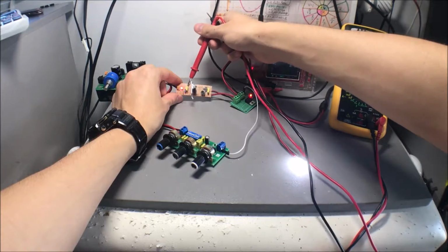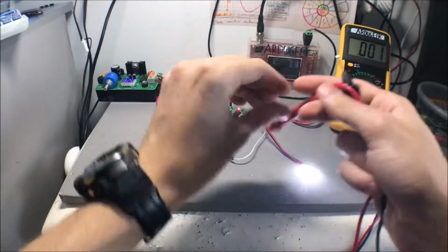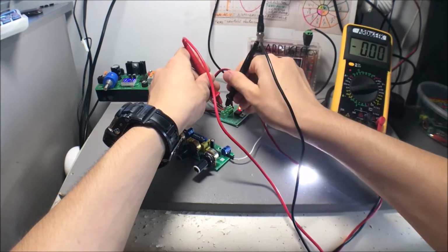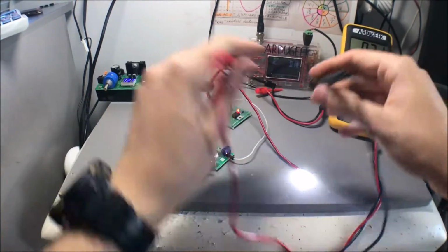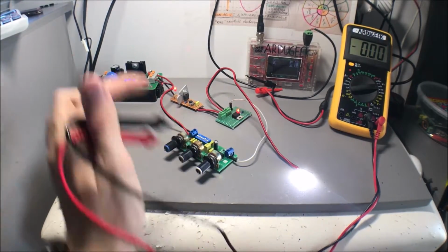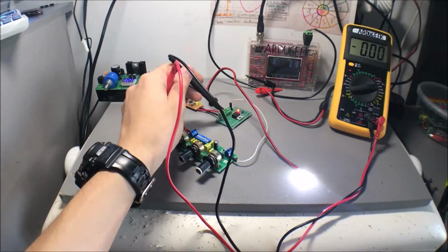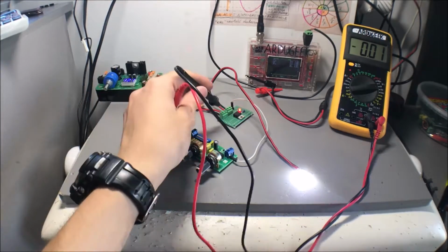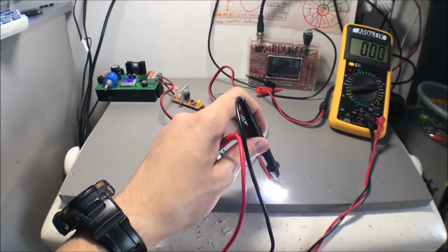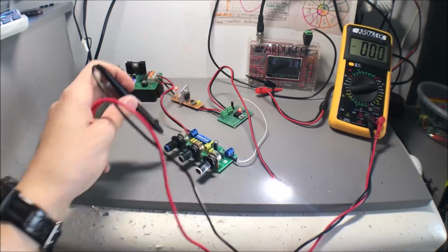LED on the input, capacitor, resistor, potentiometer, and capacitor on the output, and then it outputs the voltage. And now, as you can see, voltage is 4.3 and the current is limited to roughly 300 milliamps. So then this current limited voltage goes into the MOSFET module. In the MOSFET module we connect our load, which is our LED, this little guy, and then little LEDs for indication and the square wave generator.